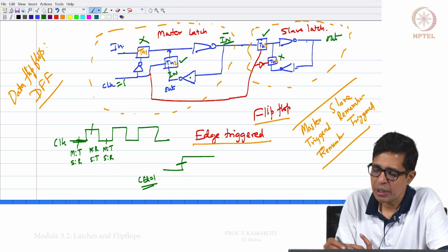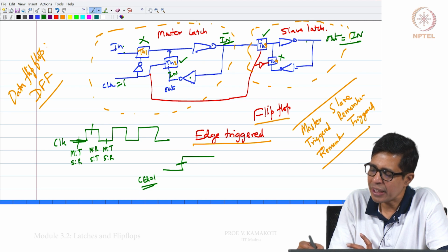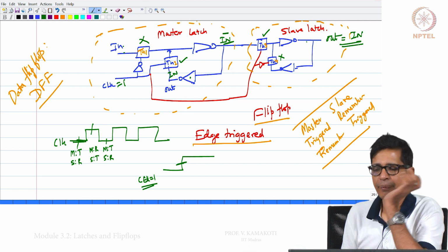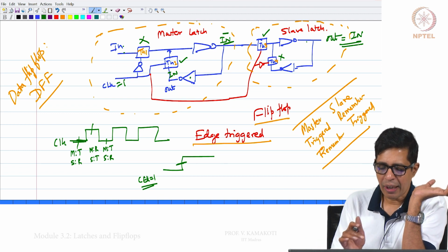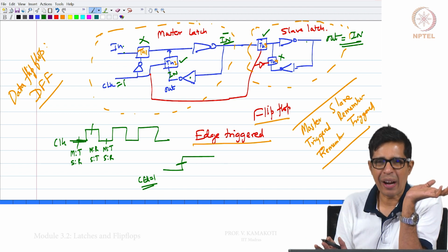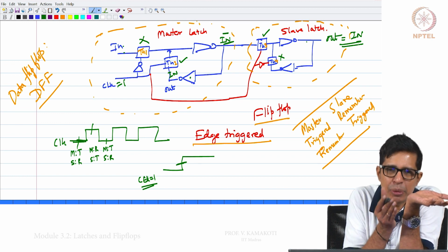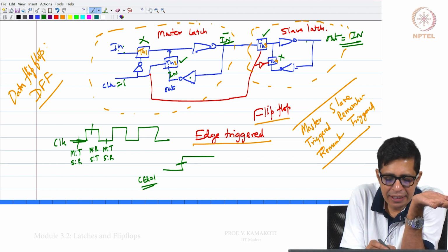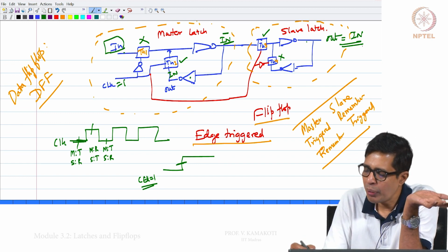This is the output. So this in bar will flow here, so the out will be equal to in, right. So, when the clock actually becomes 1, then what was there just before the clock becoming 1 in this input in, as I am marking in green here, will now come out here.